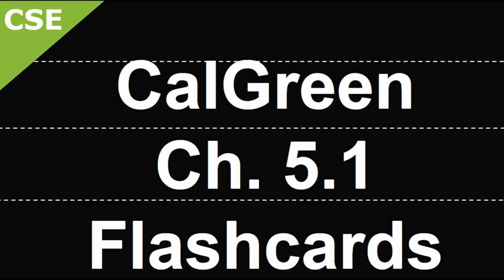Now, if we decide to install a DCFC, then for every DCFC, we are permitted to reduce the minimum number of required EV-capable spaces without an EVSE or an EV charging station with a level 2 EVSE by 5, and reduce proportionally the required electrical load capacity to the service panel or subpanel. And if you decide to install 2 low-power level 2 EV charging receptacles, then you can reduce the minimum required number of EV-capable spaces by 1.